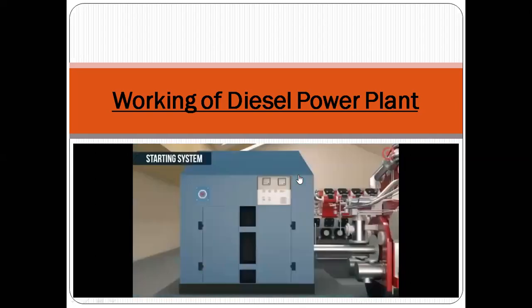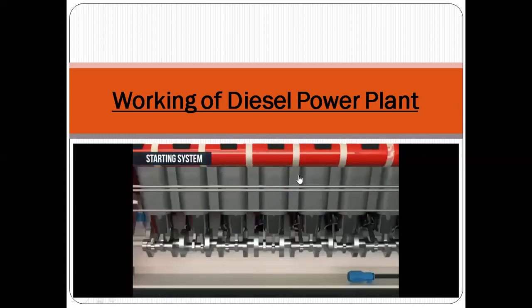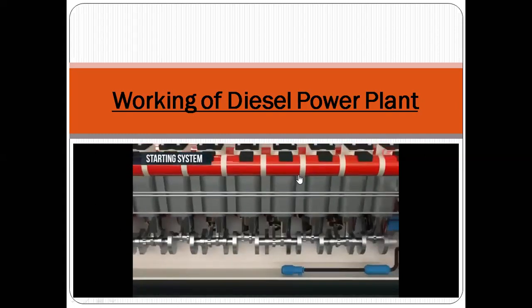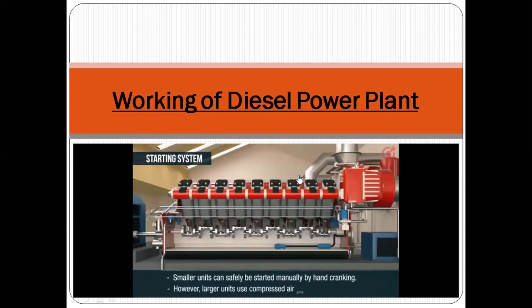The starting system. The starting system provides the initial rotation to the engine shaft required to start the engine. Smaller units can safely be started manually by hand cranking. However, larger units use compressed air for starting purposes.